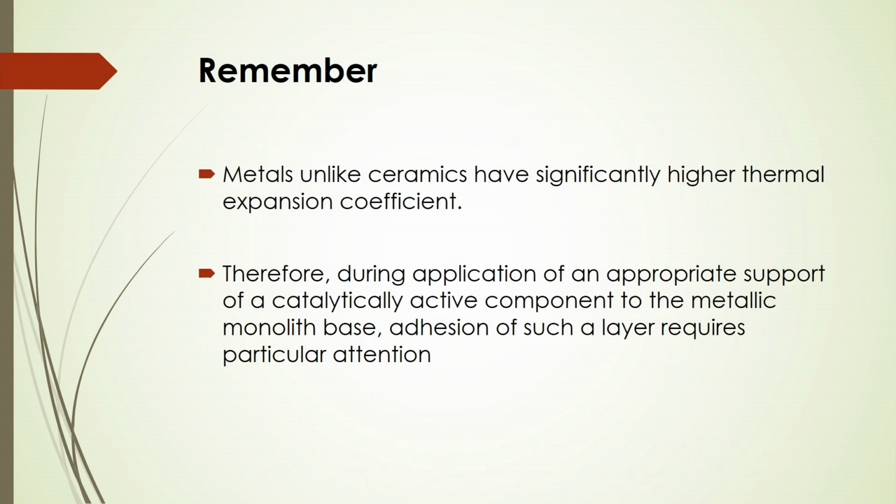In this case, remember that metals, unlike ceramics, have a significantly higher thermal expansion coefficient. Therefore, during the application of an appropriate support or a catalytically active component to the metallic monolith base, the adhesion of such a layer may require particular attention.